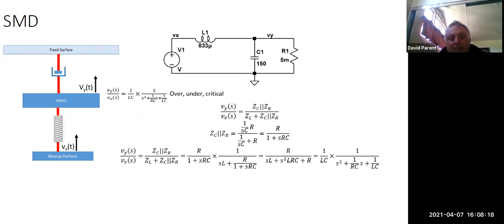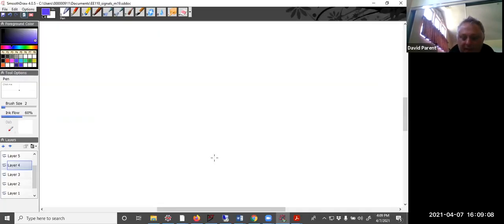So the mass has a velocity, right? And it's got to be able to move, but it's being measured with respect to a fixed surface. So whenever you draw that capacitor, you put a ground right there. Even though it looks like, and I've even drawn it, here's the mass. But notice this end of the resistor doesn't come here, right? It's all the same node, even though it looks like it's not the same node, because it went through a mass, right? This is the trickiest part, okay? Just so you know.